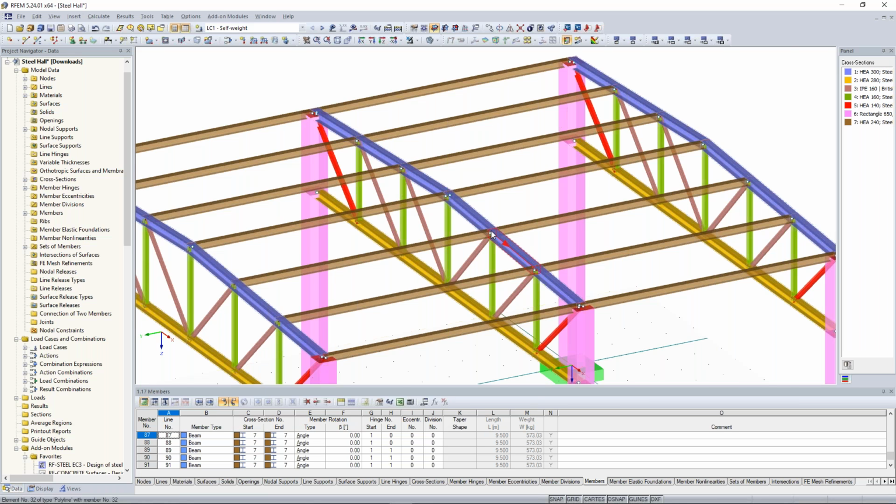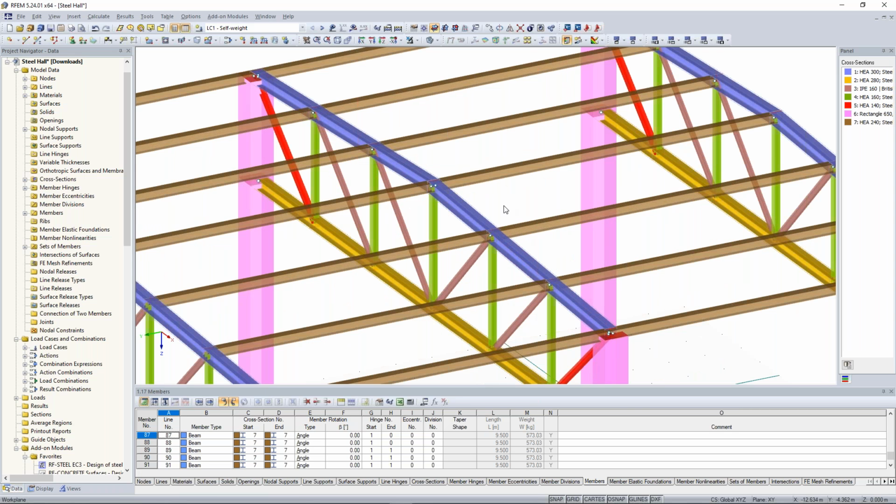Yeah, I can consider scissor hinges, and each of the two member pairs transfer moments in its continuous member direction. But they do not transfer any moments to the other pair. So only shear forces I want to transfer to that beam.